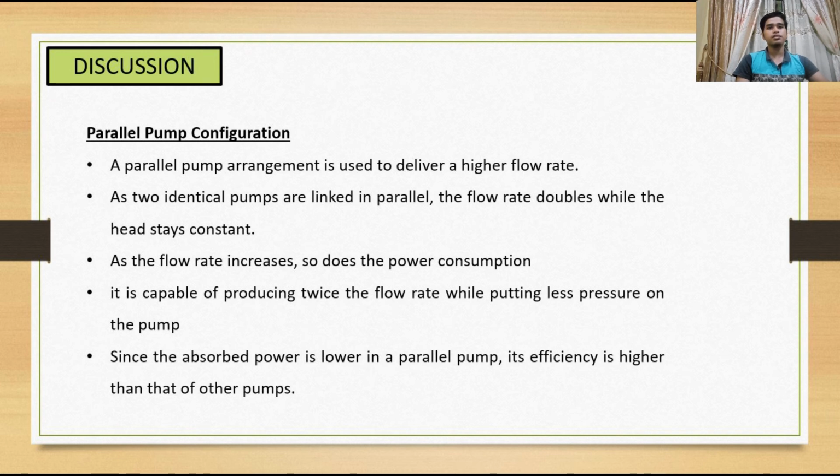The header structure that connects two pumps leads to the same pressure for their suction and discharge connections as they are joined together. As a consequence, when the pressure head is the same, the overall flow they produce is the same as the flow provided by the pumps. The overall output curve of the system is calculated by adding the flow delivered by the pumps at a certain head. Furthermore, as the flow rate rises, the power demand rises with it.